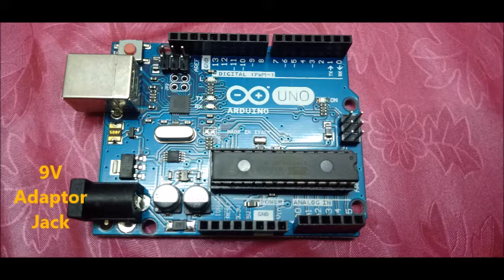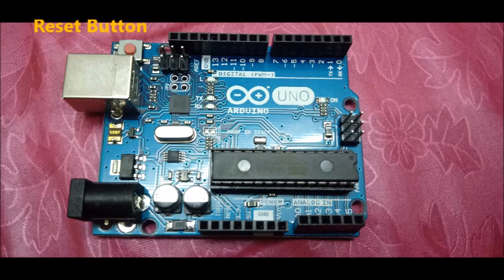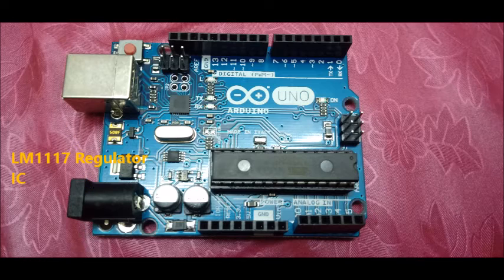Some other components are also there. 9-volt adapter jack. Here we provide a power supply. This is USB plug, a reset button. Crystal is placed on this. This is a metallic crystal. LM1117 regulator IC. It converts a 5 volt into 3.3 volt.